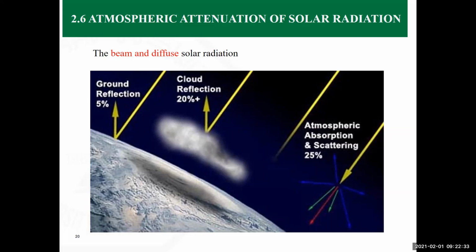It's basically for researchers or for coming up with a basis maybe for correlations that can be used for the estimation of the cooling load of a certain building, where there are internal heat sources like people and equipment. There are external heat sources like heat transfer through the walls, and there is radiation through the glass, including a part of ground reflection that can be added to the amount of heat added to the building because of the reflected energy coming from the ground.